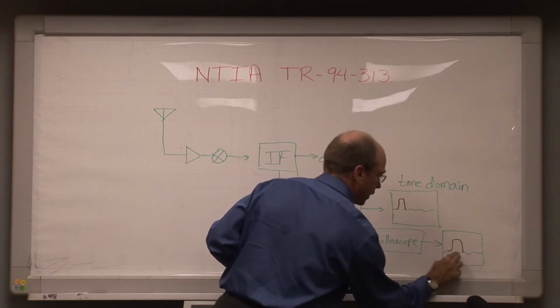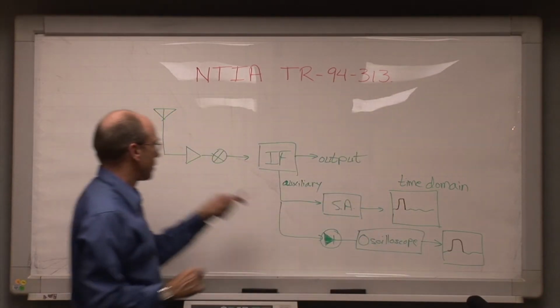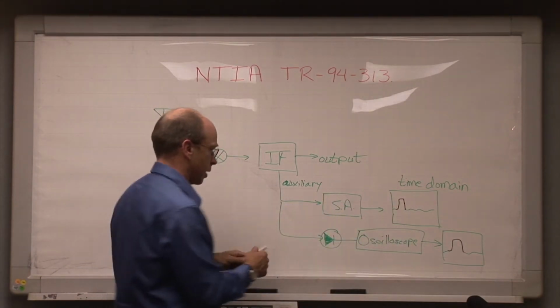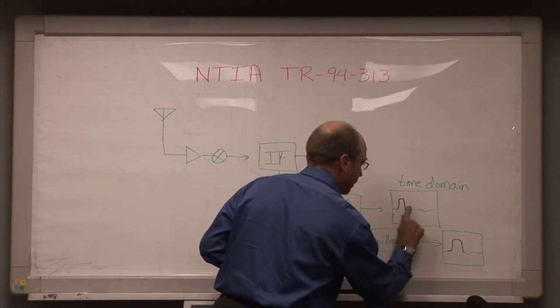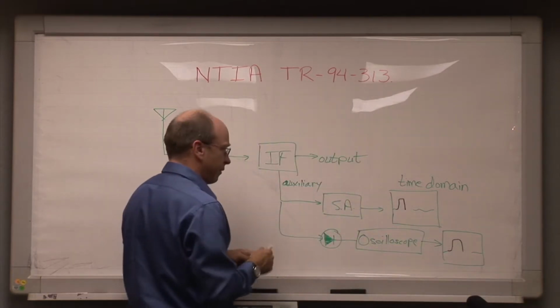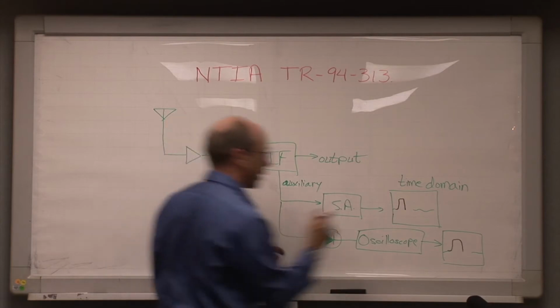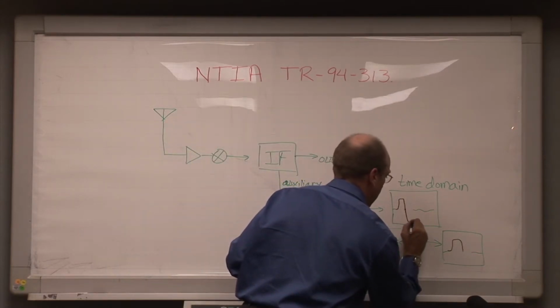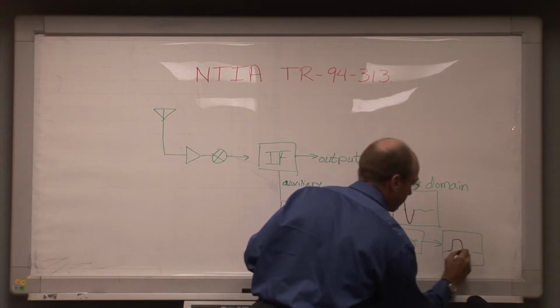We're going to see the following artifact show up. And the artifact is that after the pulsed emission from the high power out-of-band transmitter has occurred, the gain characteristic of the amplifier will have dropped, like I drew earlier, and we're going to see this happen, like so.